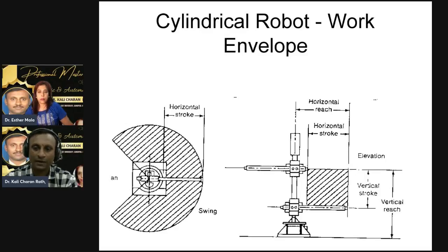At the bottom part it is a revolution, and the top part has one linear motion and another horizontal motion. R2P means cylindrical: one rotation and two prismatic. If we write 2RP, then we give two revolutions and one prismatic. That depends upon the design as per the requirement.